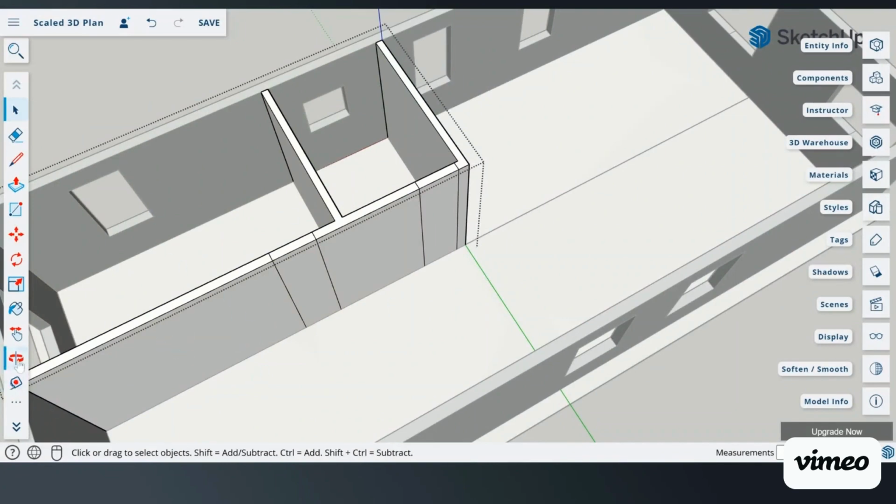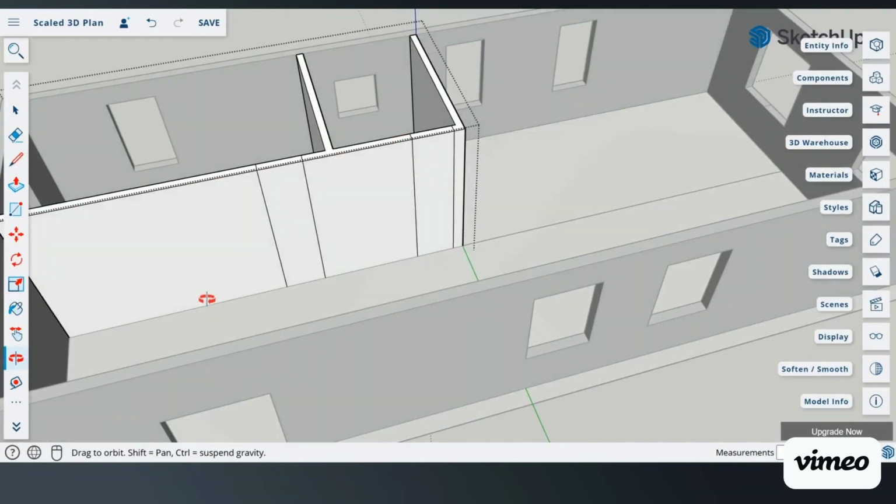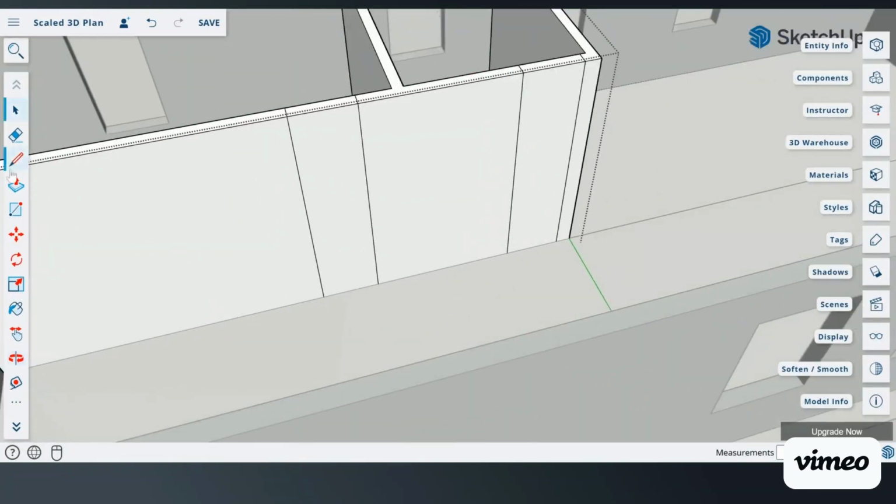Clicking on your interior walls, I'm going to go ahead and create the lines for my door openings. So using that orbit tool here, I'm going to orbit my drawing, and our doors are going to measure the same height at that 60 inches. So drafting a line up 60 inches, and then going ahead and creating my line across for the bedroom and the bathroom. Then of course we can use our push-pull to push things out.